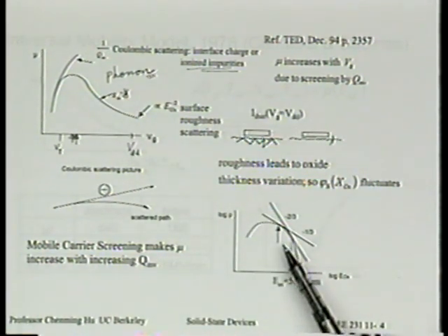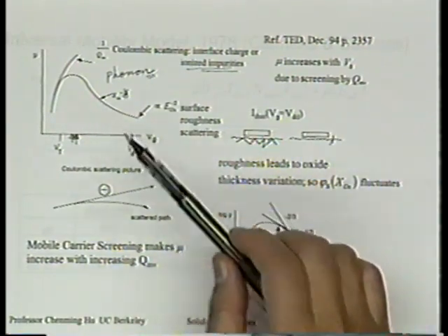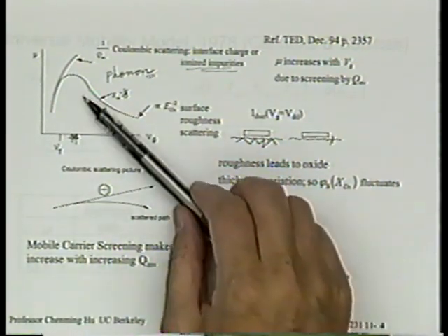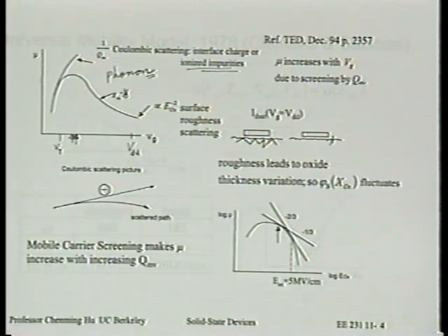Right now we have more than necessary to explain this field dependence by phonon scattering. But nonetheless, I think 95%, if not 99%, of engineers will say this is surface roughness, and I certainly also agree that there can be a surface roughness contribution. The question is, in reality, when you're given a state-of-the-art sample, how much is due to surface roughness? I think it's very, very uncertain at this point.